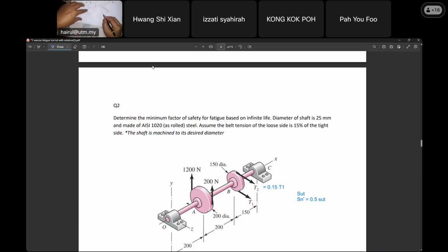Logically, at the element, if you look at my live video, this is section B. So we have torsional stress in this direction. The shaft is rotating, and this is your torsional stress. All along the circumference, the torsional stress value is the same.